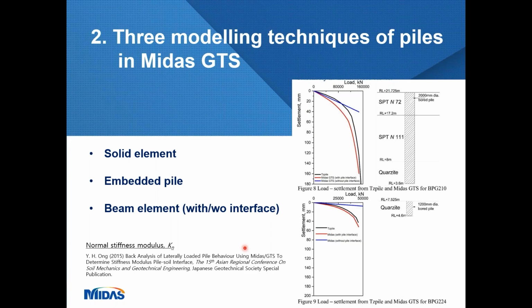Let's go into the topic today. We can model piles in MIDAS GTS NX using solid element, embedded piles, or beam element, with or without interface. You might want to master all 3 methods because you may not know when you need to use them in your modeling.